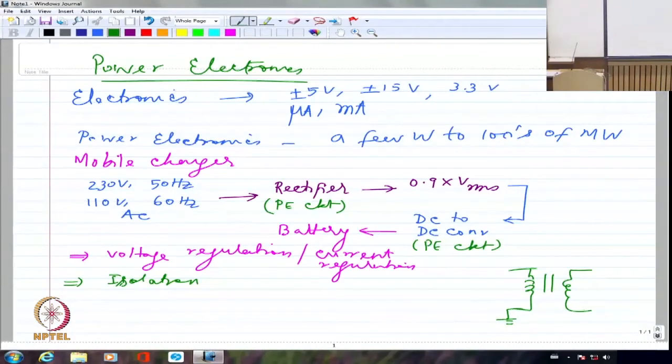Never. Right? So the isolation takes place whenever I use a transformer, two-winding transformer, not auto transformer. Right? Auto transformer is a single winding transformer. You connect primary and secondary together. So whenever I use a transformer, I am going to have isolation between the primary and secondary. Similarly, isolation will be possible when I use a power electronic circuit. Probably I will insert a transformer somewhere. Probably I will insert something else. I'll have to check what other stuff I have to insert.